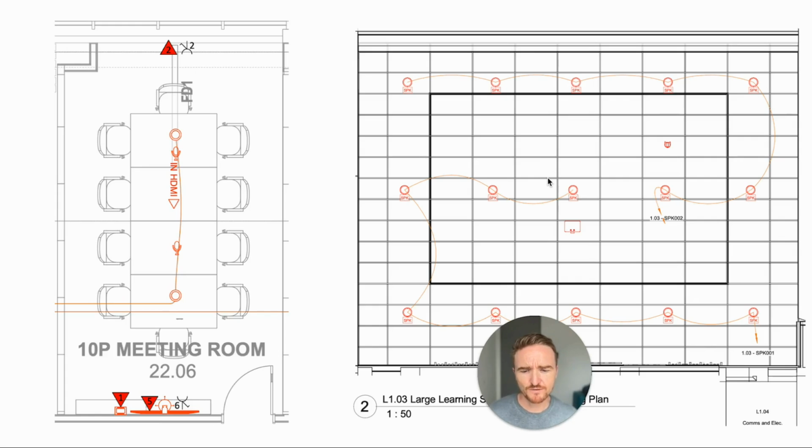So RCP stands for Reflected Ceiling Plan, and you can think of this as like a floor plan or a map of the ceiling. The term reflected in Reflected Ceiling Plan refers to the idea that the ceiling is drawn as if you're looking at the ceiling's reflection placed on a mirror placed below it.